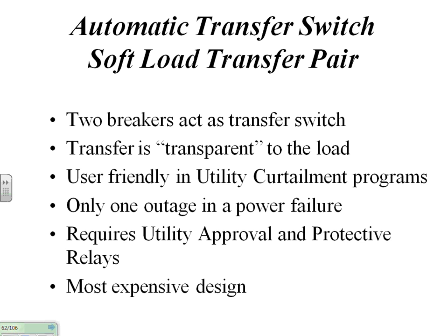And because in a power outage we only have one time that the room goes dark. Because we're connecting to the utility all the time, or for a long time, it requires the utility approval and protective relays. Again, you're going to be on our grid, this is what you need. And it's the most expensive design.